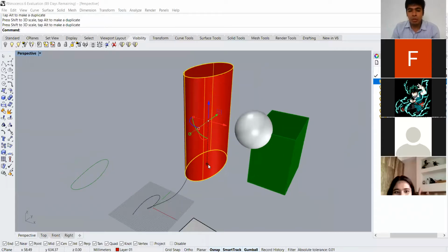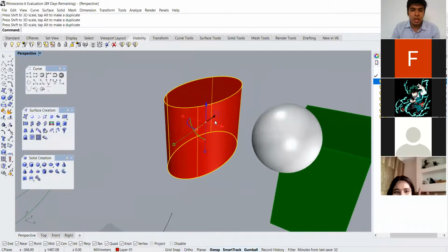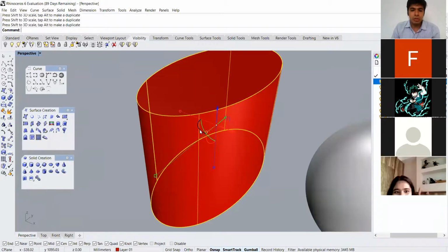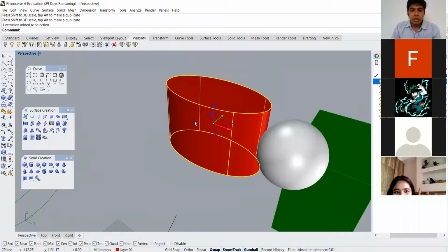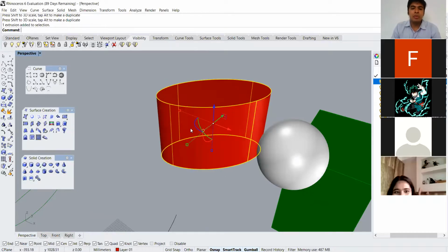Like I mean, say for the gumball, it has move, scale, and also rotate. Yes, an important one is rotate. You don't always have to find the center of an object, say an ellipse or sphere. You just select this one and type any number you want, say 45. Once the command is entered, you select here and then press anywhere.